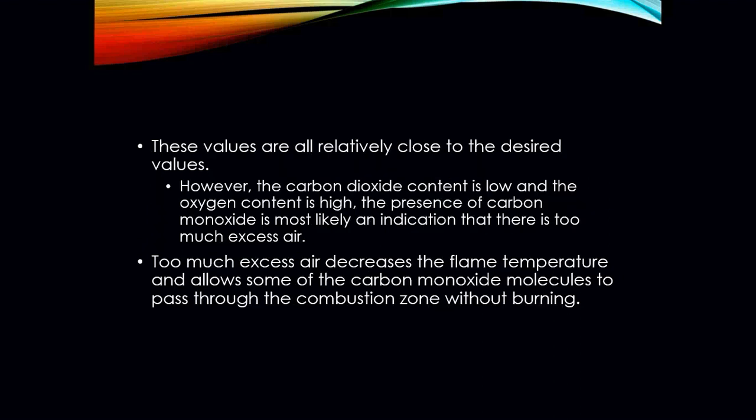These values are relatively close to the desired values. However, the carbon dioxide content is low and the oxygen content is high. So the presence of carbon monoxide is most likely an indication that there is too much excess air. Too much excess air decreases our flame temperature and allows some of those carbon monoxide molecules to pass through the combustion zone without actually burning.